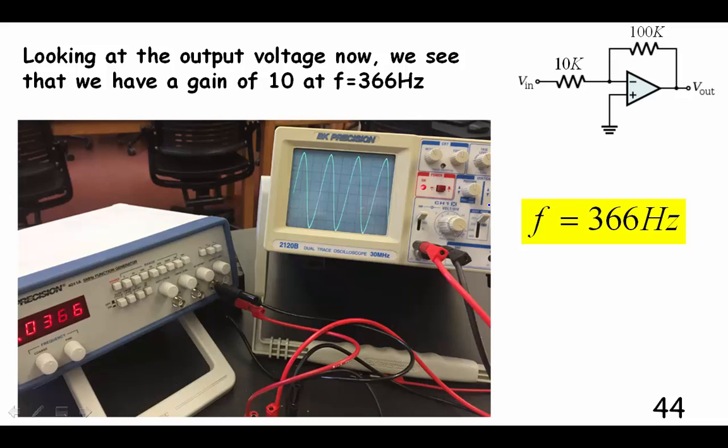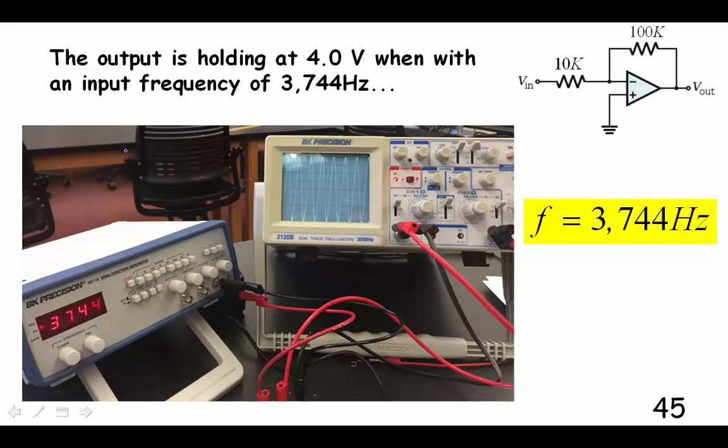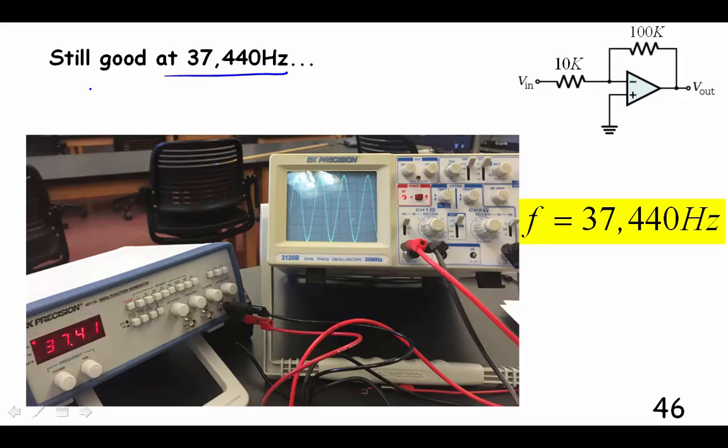And then I'm looking at the output, and I've got a gain of 10, so that means that the output should be 4 volts, and there it is, 4 volts at 366 hertz. If I'd gone lower, it would have still been 4 volts all the way down to 0. So now I've increased it to 3,744 hertz. We're still at 4 volts. Still at 4 volts at 37,000 hertz.